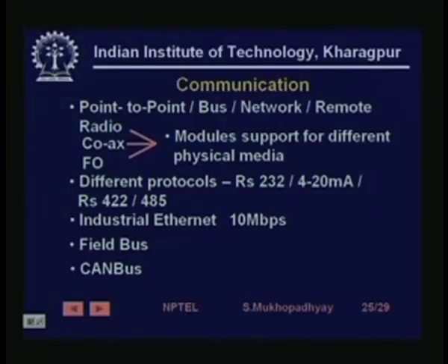There are other less popular buses, probably I can call them less popular. For example, the CAN bus. The CAN bus is much more popular in another application environment, that's automobiles. Field bus is gaining popularity in the industrial environment, and some buses could be proprietary. For example, Siemens has a proprietary protocol bus.